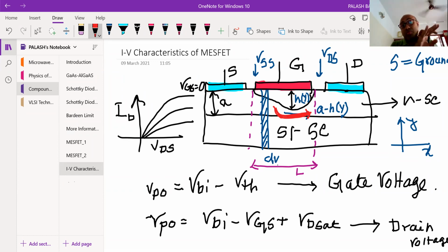The moment it goes to the interface layer, the interface of any, like, silicon dioxide interface, it will reduce to 700, 600, just approximately half. But here you see the electron is flowing across the bulk. So that means here the electron mobility of, if you take gallium arsenide, is 8500 centimeters square per volt second, which is really high.